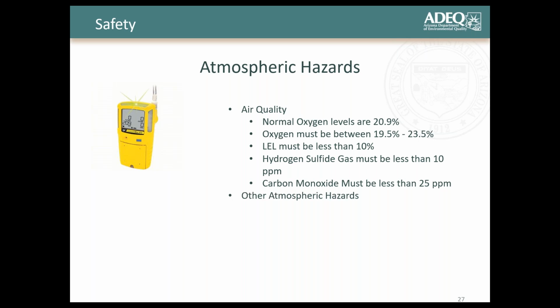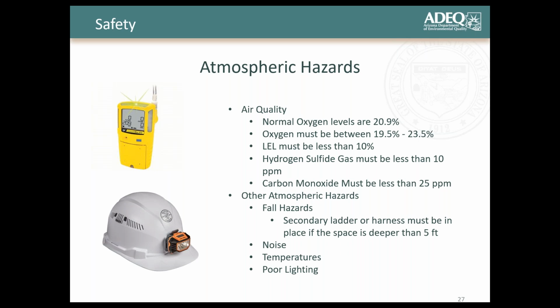Now, safety still needs to be worried about other hazards, right? You also should be aware of fall hazards, right? You need a ladder or harness if you're deeper than 5 feet. Noise hazards, temperature hazards, lighting hazards, and these are just a few of the examples that I can think of. There are plenty of other hazards out there that you totally need to be aware of in order to maintain a safe working environment.